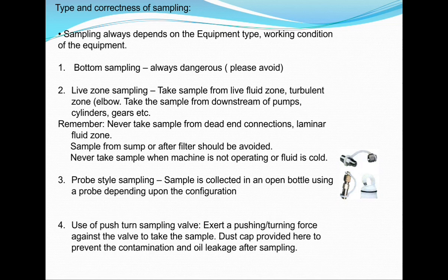Next, use a push turn sampling valve. This is another method of sampling. Here we have to exert a pushing force or turning force against the valve to take the sample. And whenever we release this force, the valve automatically stops. So this is the best way of taking the sample also. Here also a dust cap, you see from the picture, is provided to prevent contamination or oil leakage after sampling. So this is all about the type and correctness of the sampling.